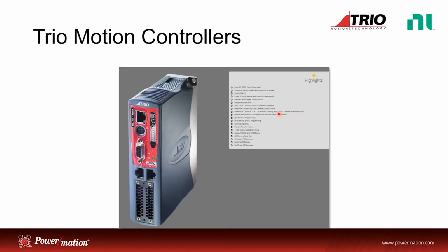The MC family, or Motion Coordinator family, from Trio Motion Control consists of a variety of controllers, everything from traditional step and direction and analog to EtherCAT control, virtually any servo system. The Trio Motion Coordinators are a full-featured motion controller, meaning you can do any kind of motion. So indexing, camming, synchronization, gearing, whatever you can imagine in motion control, you can do using the Trio Motion Controller.